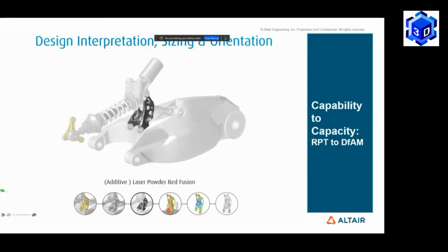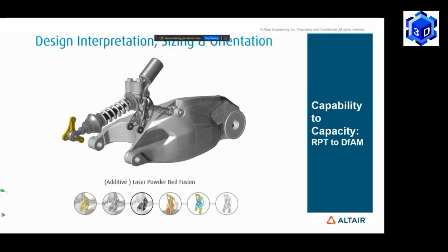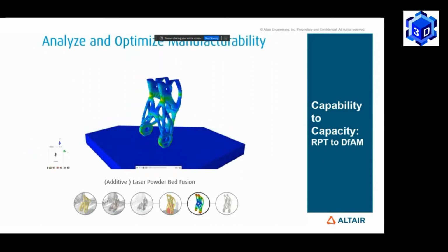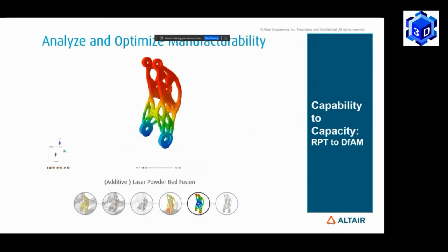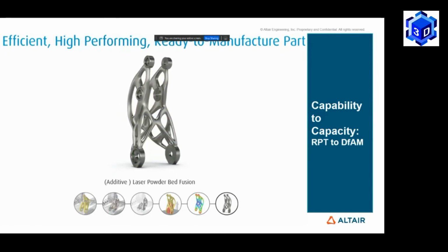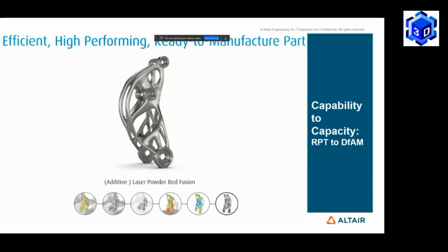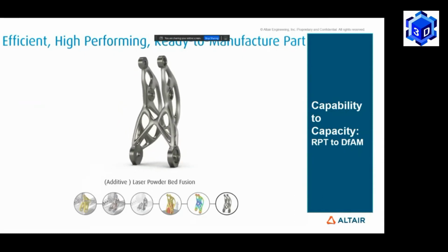And the second stage is where you are getting the shape automatically, and that shape then you are reconstructing. That has gone in the previous step, and once that reconstruction is done, you are actually doing a virtual printing here, where you are understanding that what you have reconstructed will not come out as it is after printing, because printing has its own nuances, right? You want X, but you will get X plus delta or X minus delta. So what is that delta that you want to understand?